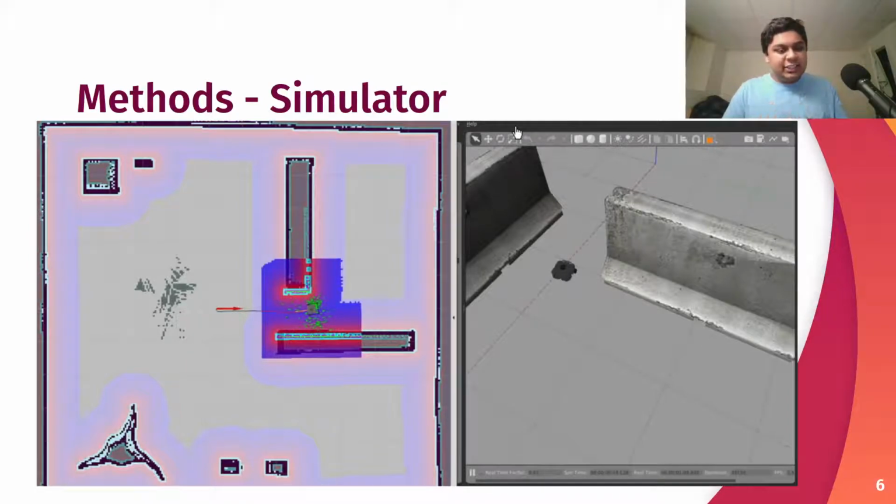So here's a look at the simulator that we used. The Turtlebot model in Gazebo comes with this nice navigation software, so I'm able to click anywhere and the Turtlebot model will go there. We collected data of both the normal data and faulty data. For the normal data, we just had it run and collect the odometry data. For the faulty data, we broke a wheel, or we had the robot crash into an obstacle, and collected the odometry data from that. Using these 2 data sets, we wanted to train TimeGAN, and then also test to see if it could differentiate normal data from faulty data.